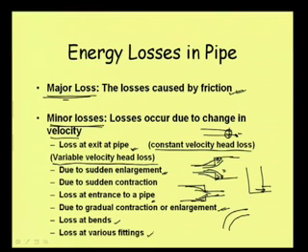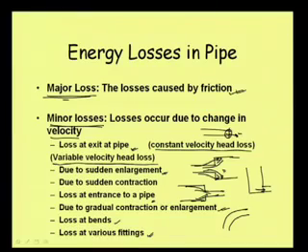And loss of various fittings. As we know, to regulate the flow we need to use a valve. At some point we use some T section. So, these sorts of various fittings we use, and when the water is flowing through those fittings, there will be a change in diameter at those points to some extent, and in those fittings also there is a loss of energy, and all these come under minor loss.